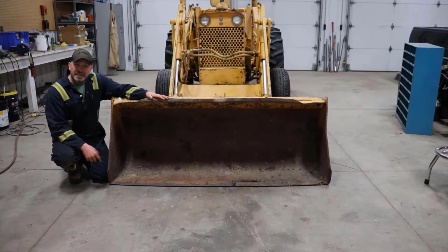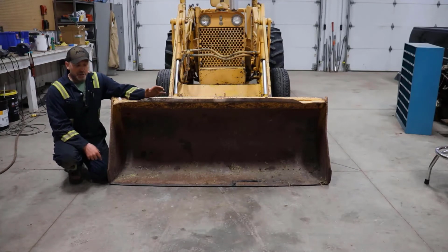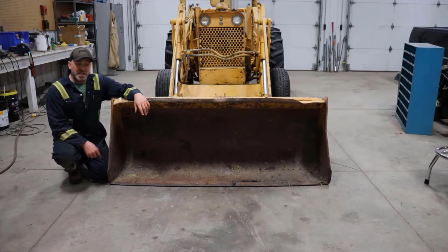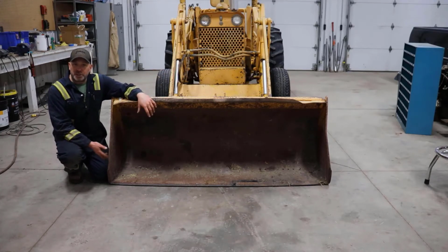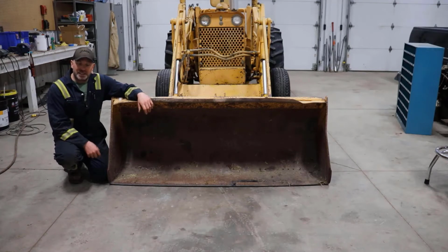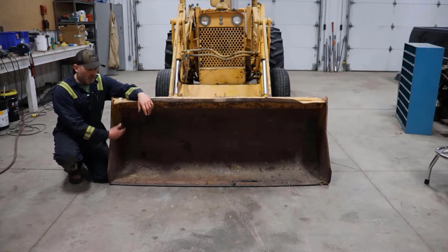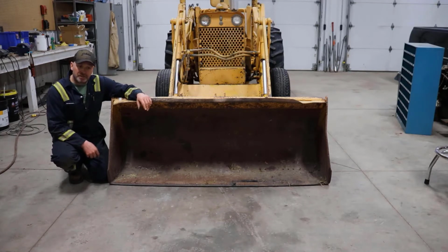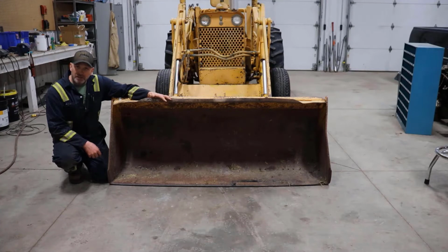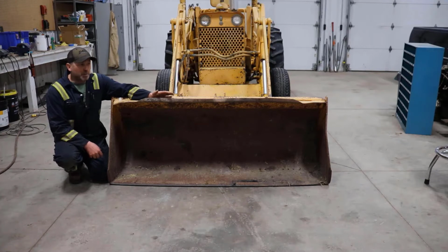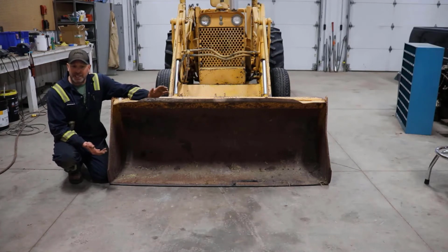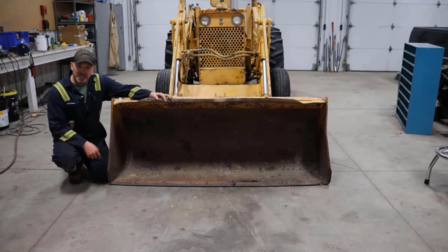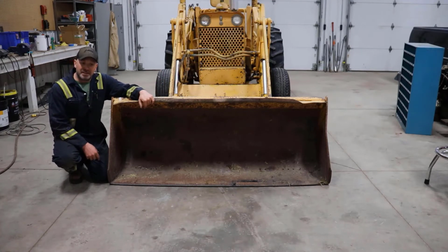The next component is force. So how strong the grapple is. If we have a grapple that's too strong, we crush and break everything we try to grab. We can't grab anything gently. We may even overpower the bucket or physically rip the bucket apart. If it's too weak, the grapple's not strong enough, can't hold what we need, and we drop our load. So if we put on a wheel loader grapple, it may be too strong for this bucket. If we put on a skid steer grapple, it may not be strong enough, and the speeds of those two machines may not be ideal.